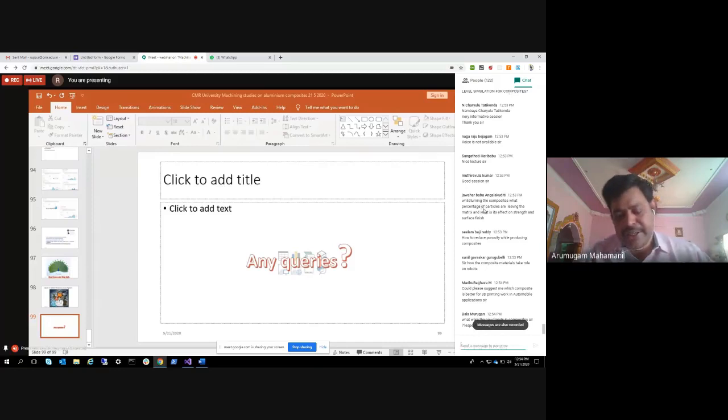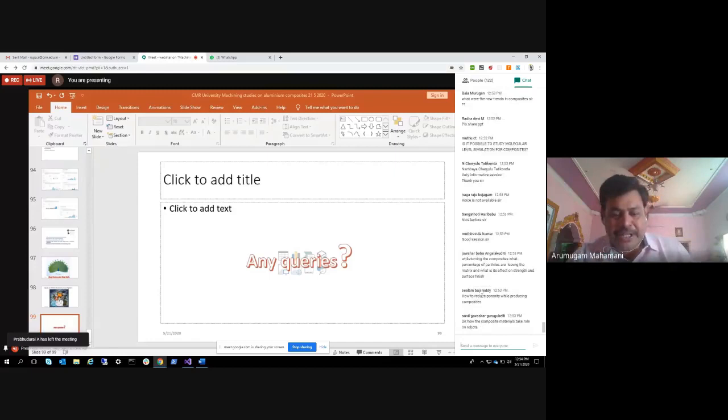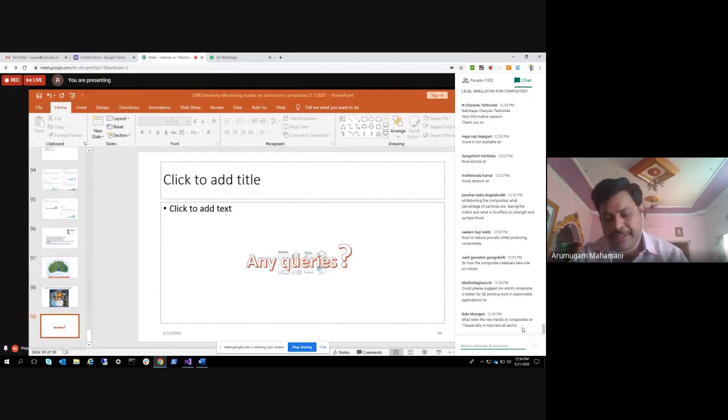Here, the one important thing is that composite materials are tailor-made. Based on your requirement, you can develop. Suppose if you want more strength, you can increase the fiber content. This is the way they are following. It's a tailorability; you can vary. There is no standard. If you go more than 40%, automatically the material strength will increase, but the workability is very important. The reason for discussing machinability issues is that the component should go for application.